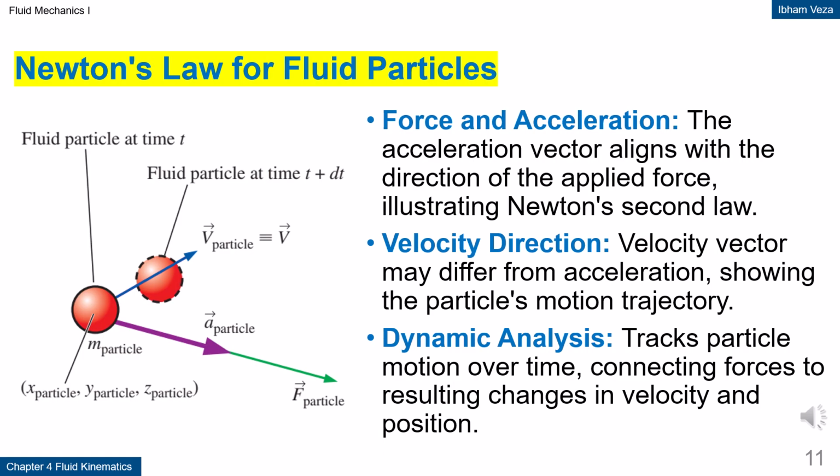Newton's law for fluid particles. Newton's law is used to explain the relationship between force, acceleration, and the motion of a fluid particle. The acceleration vector is always aligned with the resultant force acting on the particle. However, the velocity direction does not have to be the same as the acceleration direction.